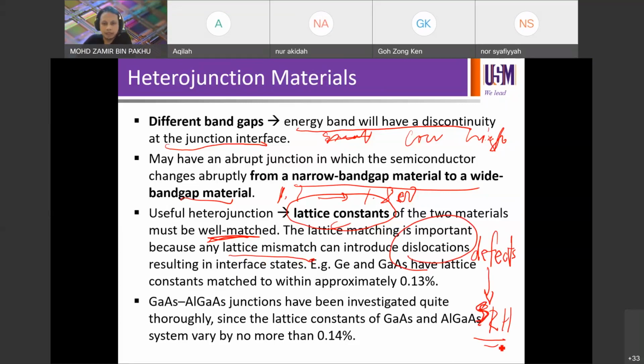Okay. So for example, defects are physical in nature, meaning you can see or perhaps cannot see them, but they are physical in nature. But if you want to translate these defects as an electronic representation, they will represent themselves as interface states in the band gap. So see, this is your EC, this is your EV, then you're going to have trap states somewhere in the band gap due to the dislocation. We already learned the other day about the Fermi energy and stuff.